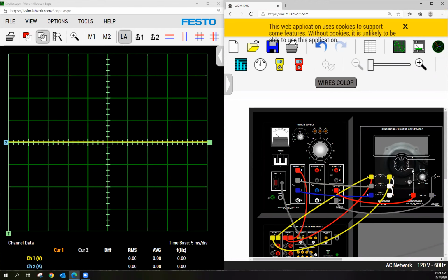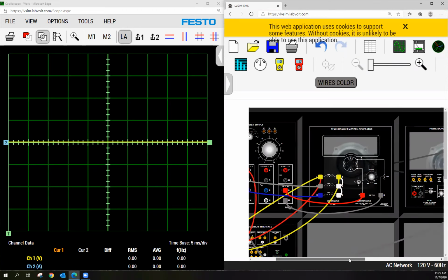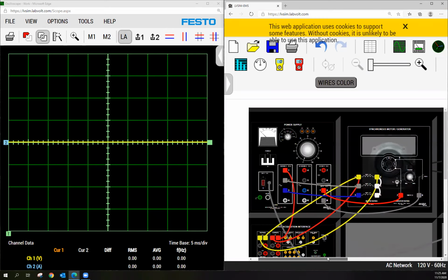Now this synchronous device has a hybrid rotor, which means it is self-starting because it has an induction rotor in the middle of it, right? Remember, if it has just a permanent magnet, it's not self-starting. If you hit it with that synchronous speed that's going ripping at 377 radians per second, or even half of that, it's still too fast to catch that rotor. But if you have an induction rotor, it'll still start up.